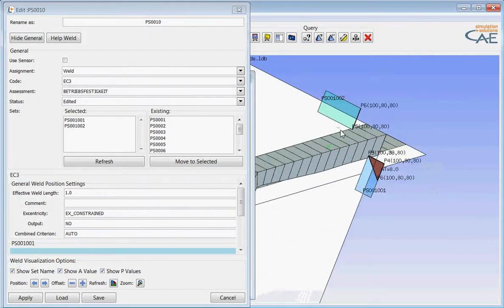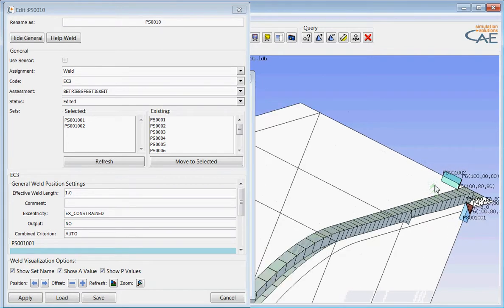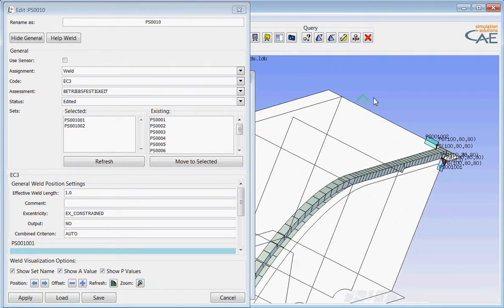Okay, so for a check, just to make sure that also the other side is welded from the right side, we can check the symbol, and this is correct. The reason why it's actually mirrored by the symmetry plane is that the shell normal of this web looks to the right, and the shell normal of this web looks to the left, so topologically both welds are similar.